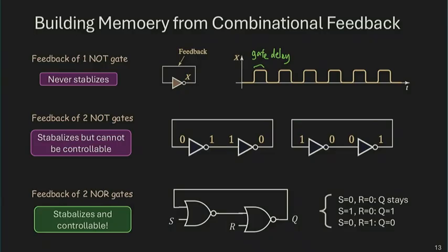So let's say, based on the first picture, the output of the first inverter is a 1, so 1 goes to the second inverter, becomes a 0, 0 comes back. So these two inverters can stabilize at this condition. They can also stabilize at the other condition. If you start with a 0 over here, 0 becomes a 1, 1 comes here, becomes a 0. So again, it stabilizes.